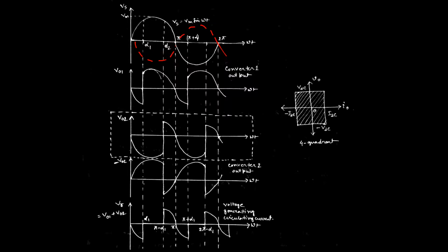And we can draw the total output voltage from converter 2 from this dotted line. So this waveform we have drawn can be converted in terms of minus VO2. Actually, we should focus on shaping the waveform minus VO2 apart from VO2. But to plot easily, we consider this as VO2, which has been taken from this waveform. In case of minus VO2, what happens? We can take the mirror image of this one, so it will give this kind of waveform.